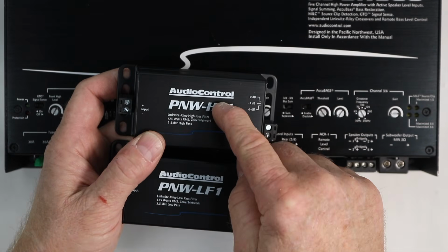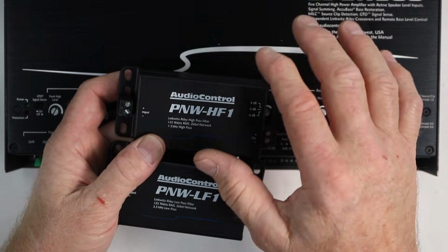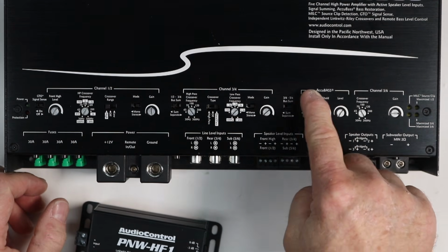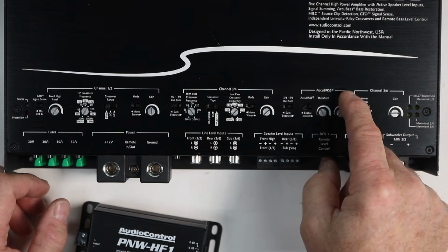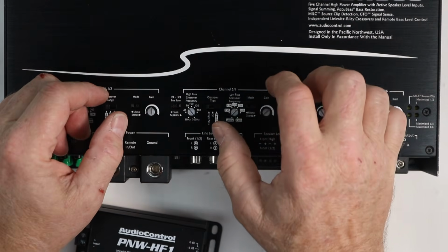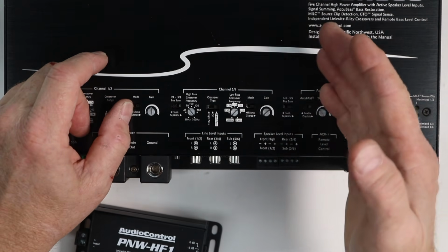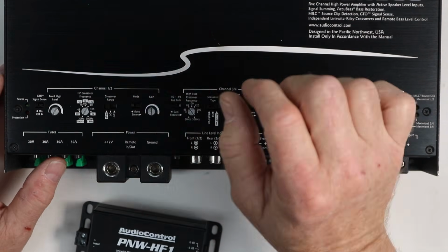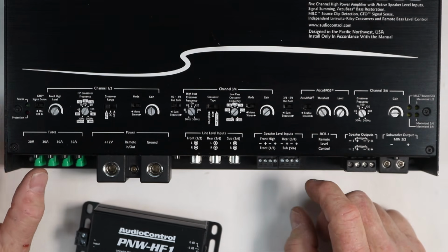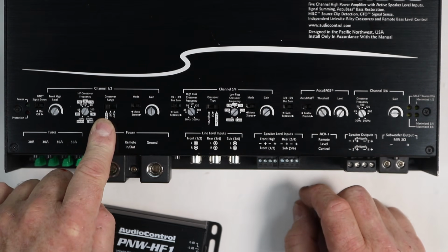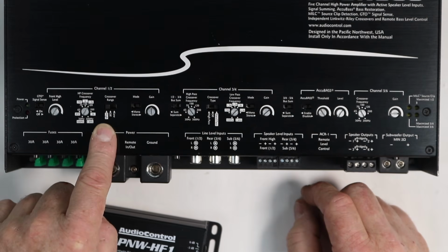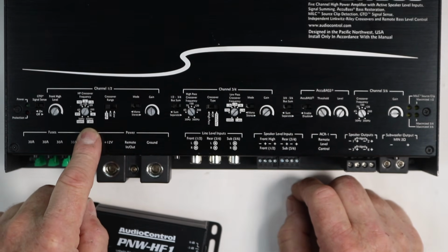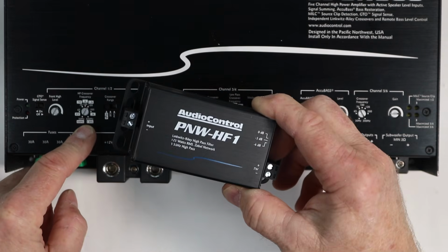Okay, tweeter is typically crossed over somewhere in the range plus or minus of 3200. So when looking at your amplifier, it has to have a crossover value of 3200. And that's kind of where the problem happens, is that most amplifiers don't do that. They top off at like 220, 250. That's not going to be enough. That's way off. Some amplifiers have a 10-time multiplier switch. Like this guy right here has a crossover range of high and low. The high goes all the way up to that 3K that we need, so that will solve the problem of this guy. We won't need it.